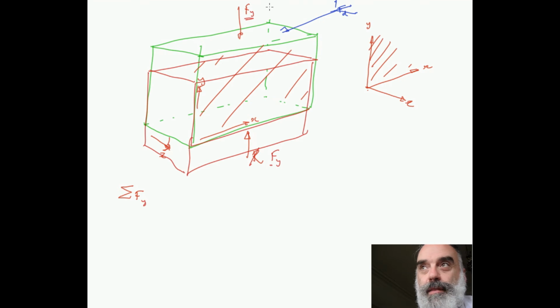If it was in space, for example, if you were designing a space station structure, which you may well be, that would continue to move until some other force came in and acted in the other direction. But for most civil engineering structures, we hope that they're going to be stationary. At some point they may settle, this bench may settle into the ground slightly, but at some point it will reach a state of equilibrium in the vertical direction. So the sum of all the forces or actions in the y direction will add up to 0.